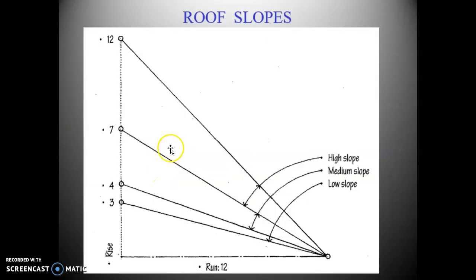I don't want you guys ever to start worrying about slopes, as far as memorizing the angles of slope. What I want you to realize, though, is when we start down here into the 3/12s, we'll consider these low-sloping roofs. 4/12s are going to be medium all the way up to 7/12s. Above 7/12 becomes a steeper slope roof. This is important because when we select a roof in particular areas, high snow, high wind, high rain, things like that, the slope really is a factor.